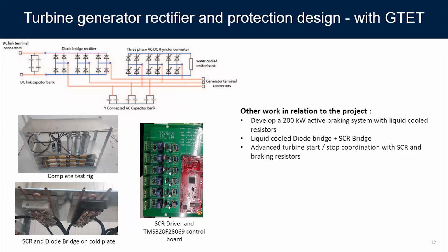For example, a low speed machine might be running at 50 Hertz or 30 Hertz, between that range, whereas the high speed machine, the fundamental is above 1000 Hertz. So you need high power electronics or specialized power electronic converters to handle that kind of fundamental frequency.